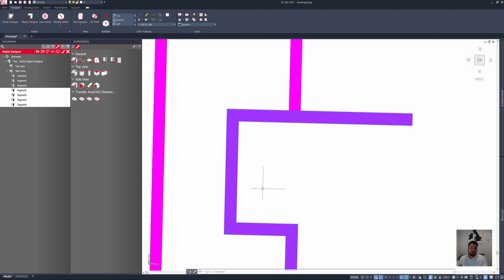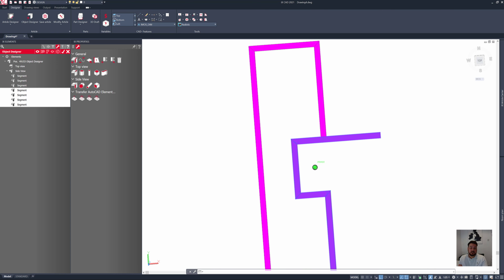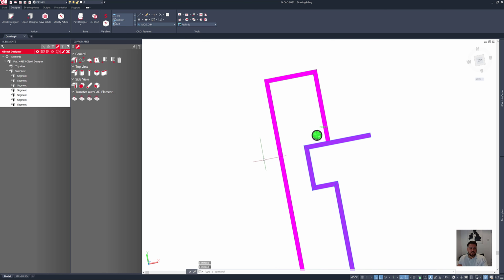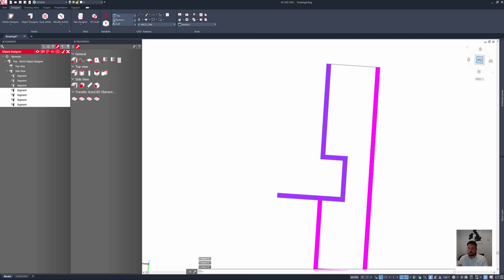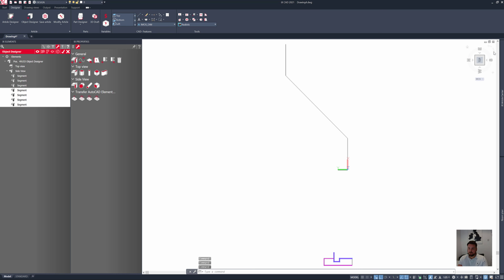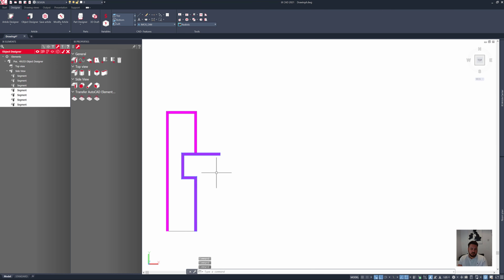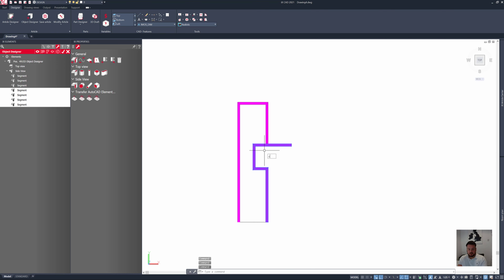Another feature that's been asked for is the ability to add cable access or machine into the center of this. So what I'll do is go into a top view again, rotate around, and draw in here maybe a circular pocket. I'll use a circle command from AutoCAD, come down here 100 millimeters and use a radius of 50 millimeters, and that's going to be my cable pass through or whatever.